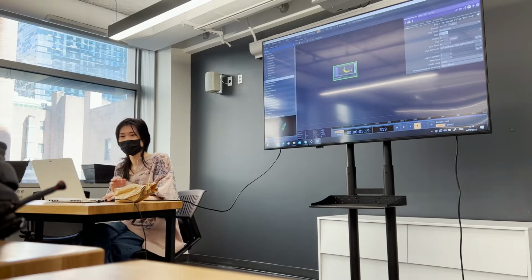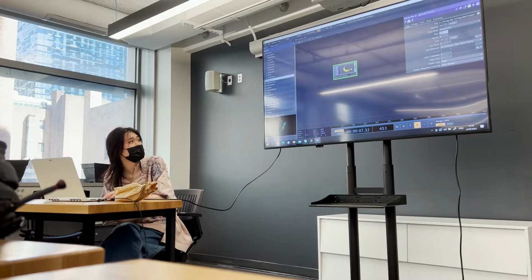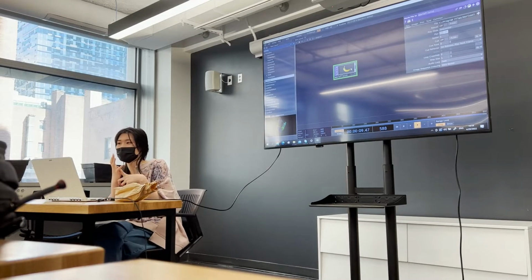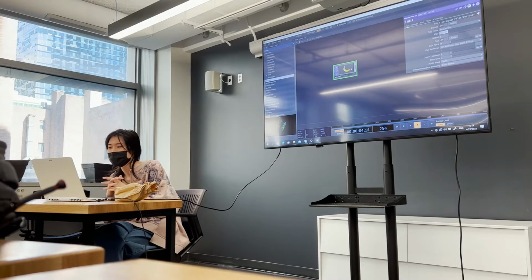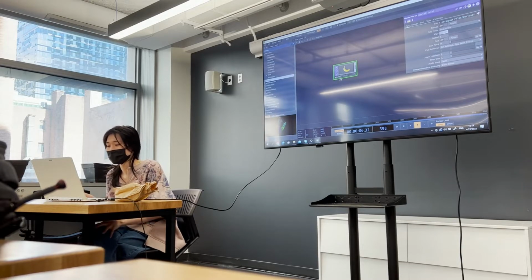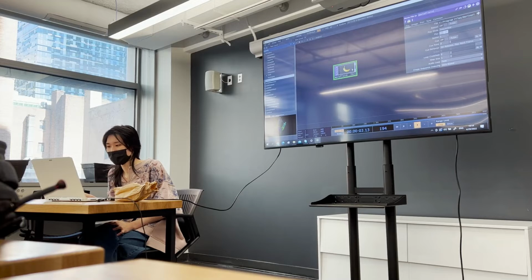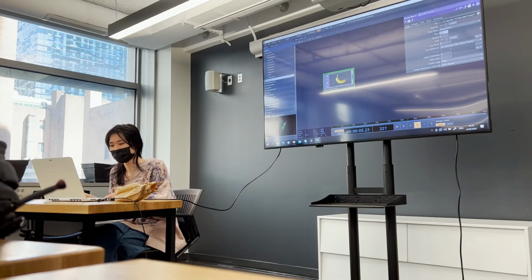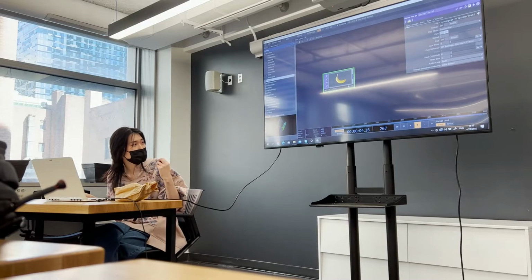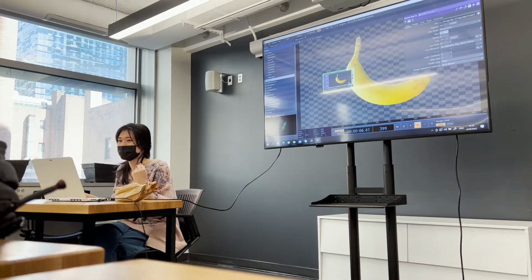The purpose of this talk essentially is just to bring in an external movie or photo or JPEG or PNG, whichever format it supports, into TouchDesigner. And this is a static image. Also, one thing I forgot to say is that if you click on this tiny blue button underneath, which I think all TOPs have, you're going to display it in the background.